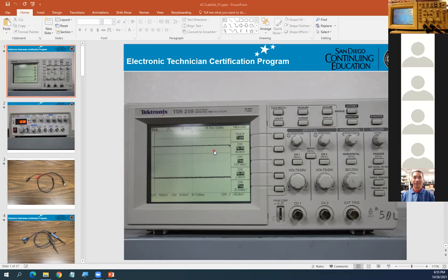Right. Okay. So that tells you one thing: when the signal is too big, you had better use the scope probe by 10. Normally, we don't have to measure very high voltage, so that's why we're using by 1. However, by 1 or by 10 doesn't matter. You have to make sure that if it's by 1 on your scope probe, then in your oscilloscope you must set the same.